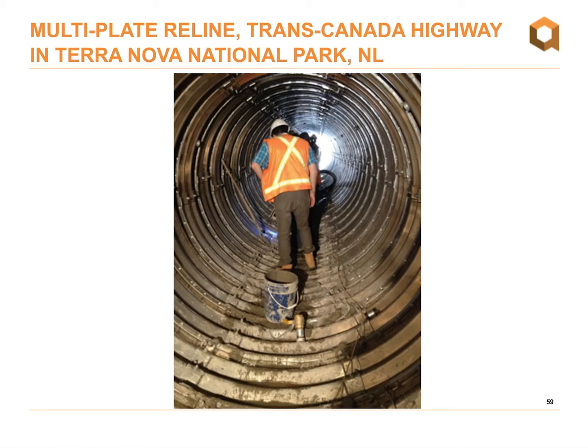The crew of 3 assembled 5 plates inside the structure. The final top plate was then put into place to complete the first ring, and simple 2x4s were used as blocking to ensure uniform spacing and proper alignment of the reline pipe. The second ring was assembled with 5 plates and moved into place adjacent to the first ring. Once again, the final plate was placed into the top position.